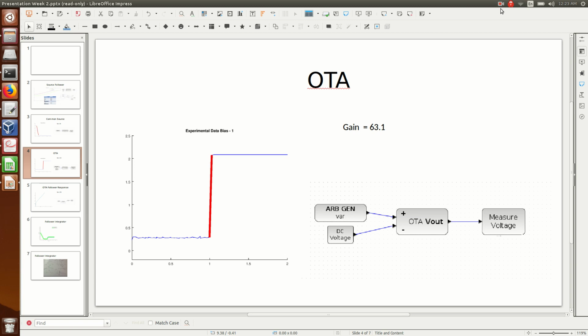What happens when we increase V plus over V minus is that I1 increases compared to I2, which then obviously increases I out, because I out is equal to I1 minus I2. This leads to V out increasing by a factor of kappa over sigma 1 plus sigma 2, but we only see this in quite a small region either side of when V plus is roughly equal to V minus. This is because the output current has the form of a tanh function, so outside this small range, the values of the output current become constant.